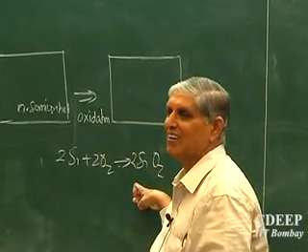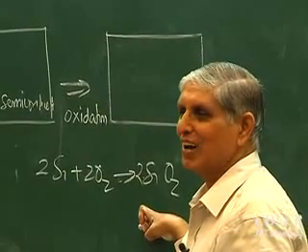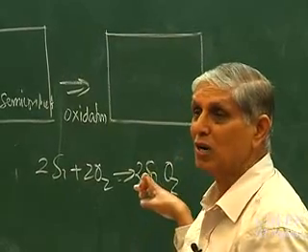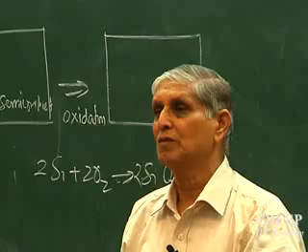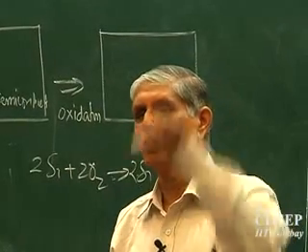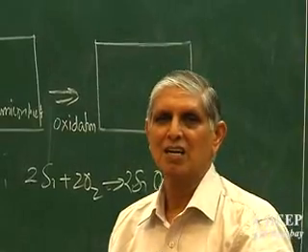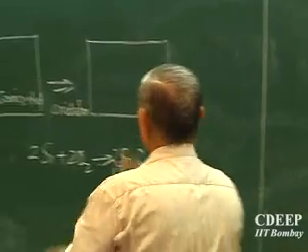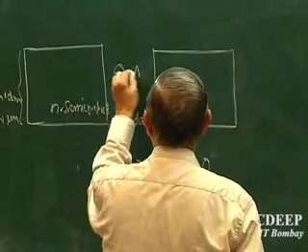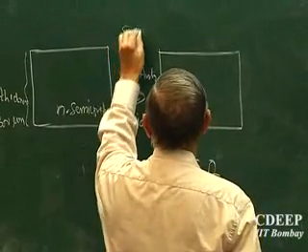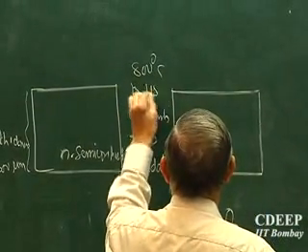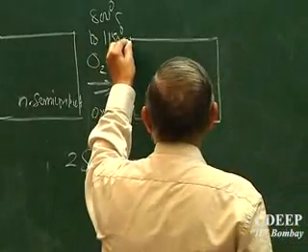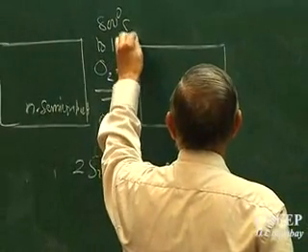We are still working on oxides. Silicon dioxide is a very tricky material, and it's one of the best materials available to us for what? Mask. What does that mask? Silicon dioxide does not allow impurities to go through it. Is that correct? So SiO2 is an excellent mask. It is very good because whenever I heat this wafer in oxygen ambient, say around 800 degrees centigrade to 1150 degrees centigrade, depending on the temperature and time I keep,